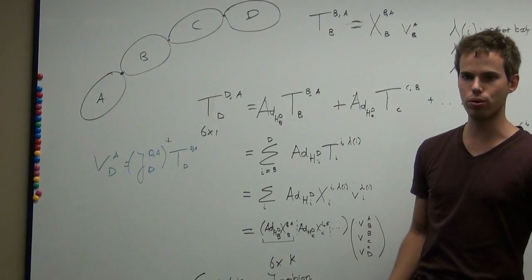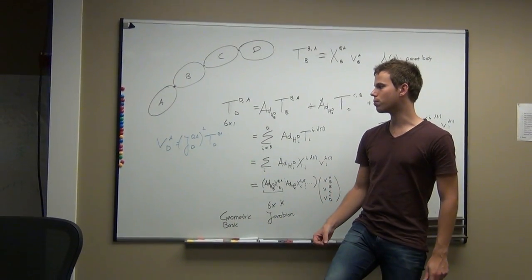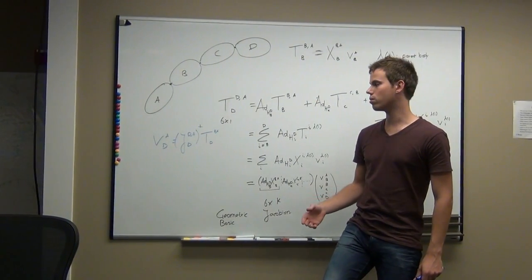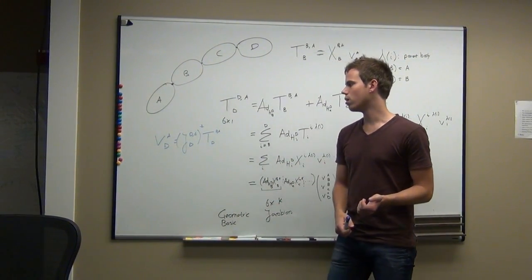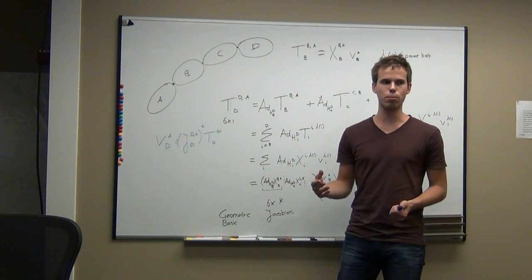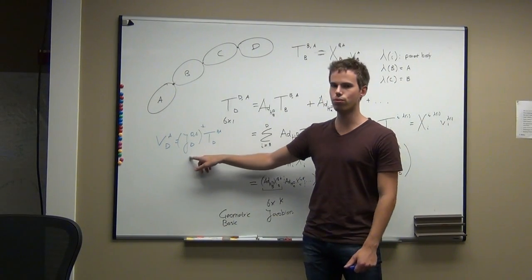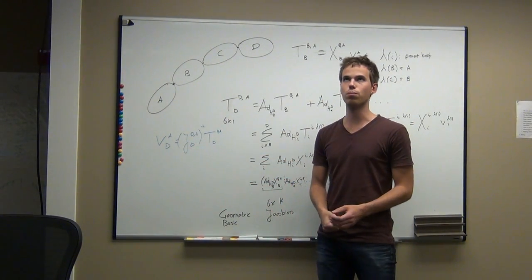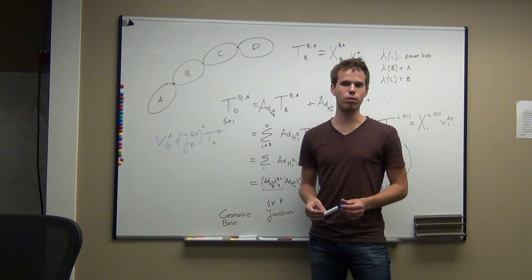You'd first have to bend your knee a little bit to get out of this singularity, so that you can actually achieve the twist of the foot with respect to the pelvis that you want. A singularity shows up as a singular matrix. So if the inverse of this Jacobian doesn't exist for a 6 degree of freedom mechanism, then you're in a singularity.